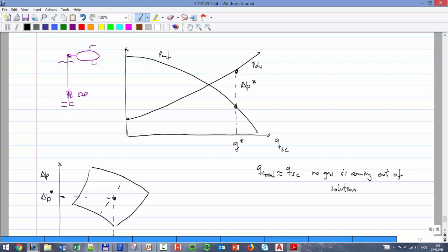The intersection, what did we say? Time affects which curve? Does it affect the tubing and the separator curve? No, right? The pressure at the separator will always be the same. So depletion will affect reservoir pressure, which means this curve here. As we discussed before, reservoir pressure affects it in a way that makes this go down.